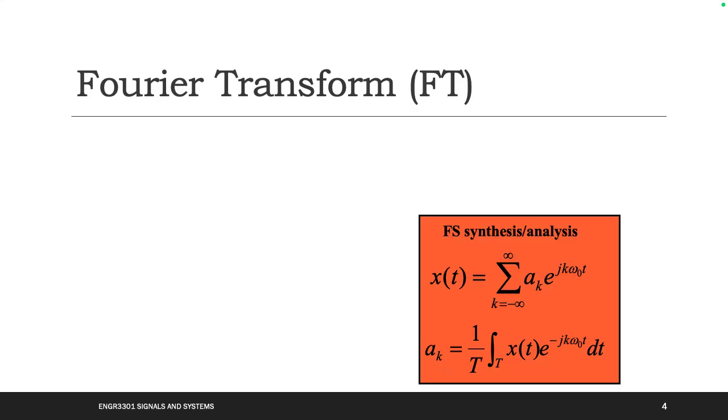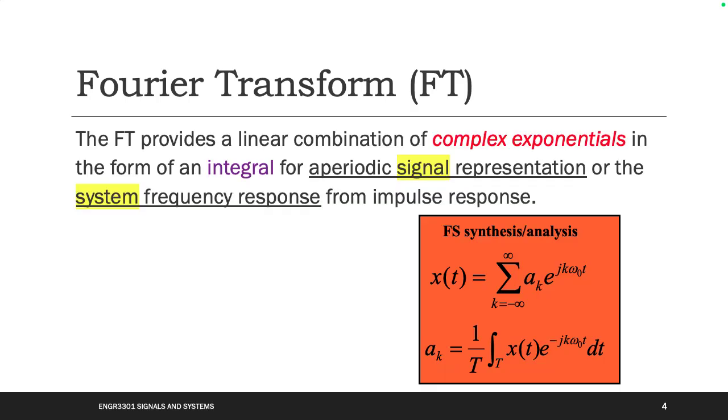And let's talk about the FT. You will find it's very similar. We spent a lot of time on the FS representation. For the FT, you will find it's very similar. The FT provides a linear combination of complex exponentials in the form of an integral for non-periodic signal representation, or the system frequency response from the impulse response.